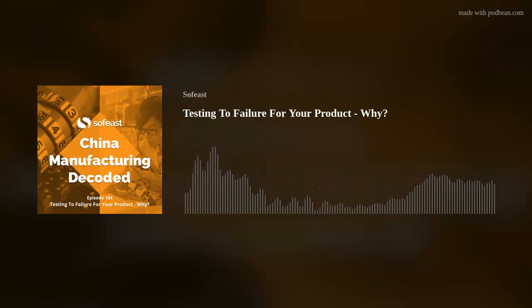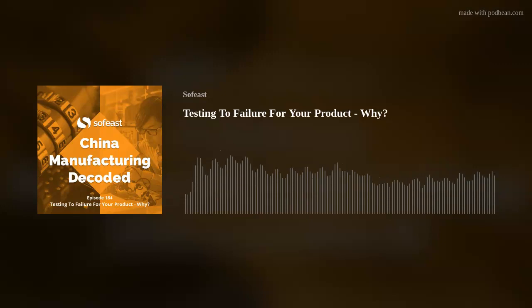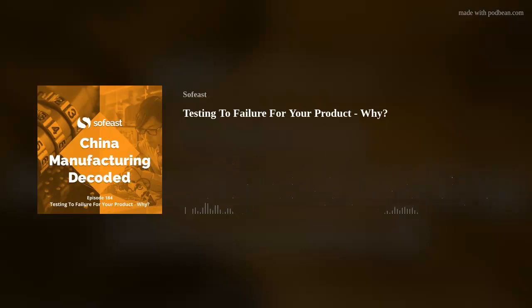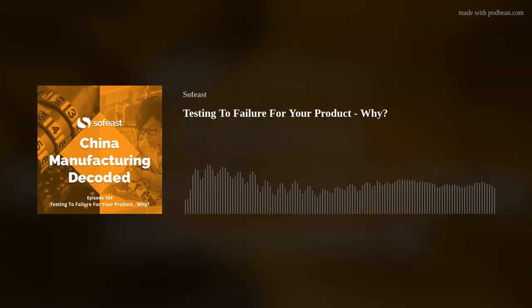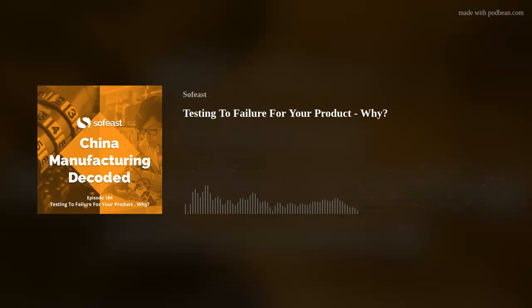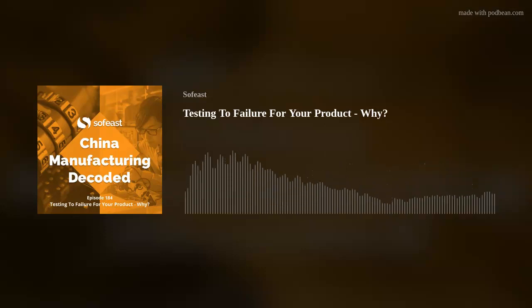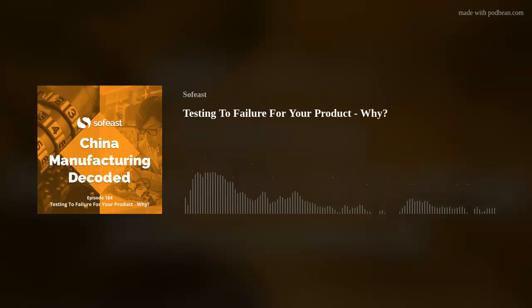So you need to push that so that you can say, okay, its operating condition is 100 volts, but it can go up to 120. No problem, no failure. You see? So now you have roughly 20% margin of failure. And that is the reliability. Basically, you have enough margin in there so that it's not going to quickly fail if the voltage is fluctuating between 100 and 110. Yeah, okay.